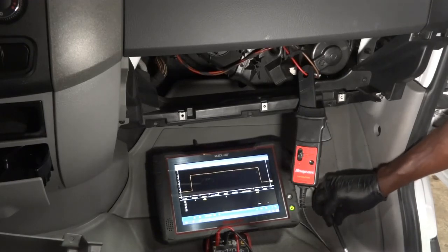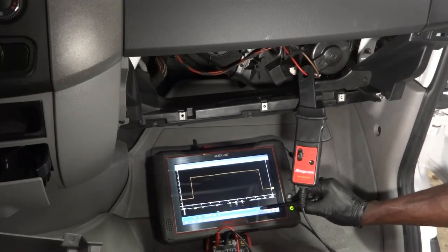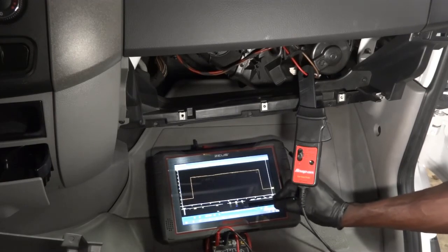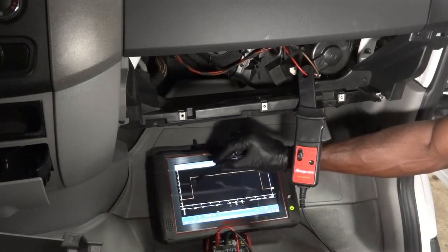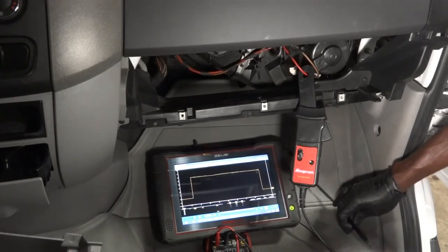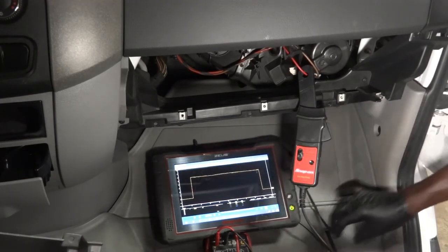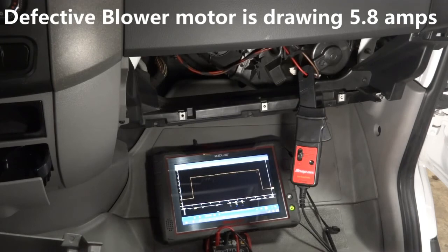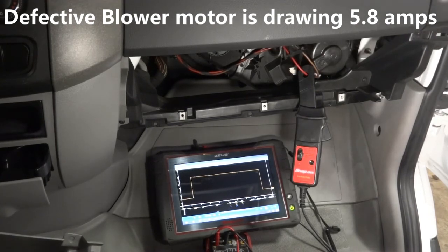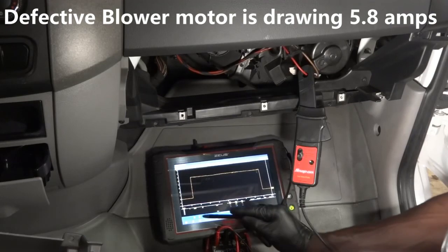Okay, so this tells me that the blower motor is shorted. And then our max here, the peak here is 5.8 amps. So once you turn this blower on, it immediately pulls about 5 amps. So 5.8 amps, which is a lot for this blower motor. Okay, so shorted blower motor.